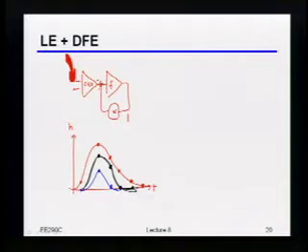More questions? Yeah. So basically, here you could make the first pole of the equalizer half of what you would otherwise. That's right. Roughly speaking, yes. Now, it's not exactly a factor of 2 because it obviously depends on exactly the channel and things like that, but ballpark, that is indeed what it ends up to be. And you can imagine if you cancel even more of these things, you may even be able to back off further, right? Although, for most channels, there are diminishing returns after that point. But indeed, there is about that factor of 2 that it buys you in terms of the bandwidth of that linear equalizer.